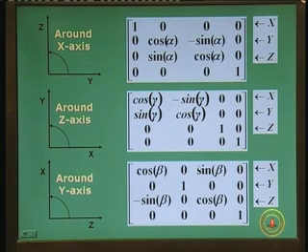If you had put the negative sign in the first row of the third matrix, that would have resulted in a rotation from x to z, but you want the rotation from z to x. If you want rotation from z to x, put the negative sign here. It is something like talking of actually a clockwise rotation, a negative rotation in some sense, to maintain the consistency.